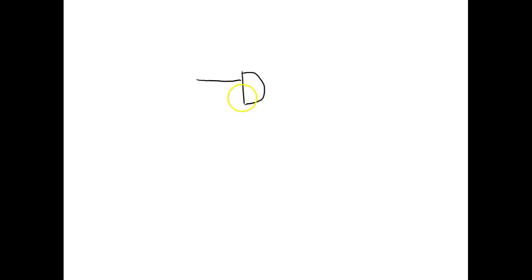So normally when we use a switch in digital, we have to supply a true. So if I came over here on TTL and I put that switch right there, if it was open, what would the gate see it as? Now we'll learn this later on. It's nothing. It'd be what we refer to as a floating input, which is not good. Okay, y'all understand that?